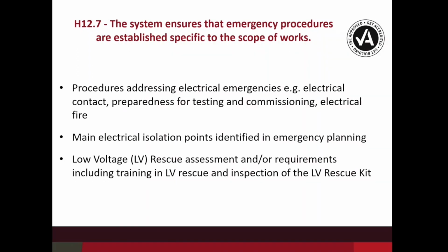Now, low voltage rescue is one that keeps coming up, and we see low voltage rescue kits and things like that being purchased and put around sites. An LV rescue kit is designed to extract a person who is currently already being energized or is under suspicion of being energized. You need to have specific training in LV rescue, and that kit also needs to be suitably tested and validated every set period.